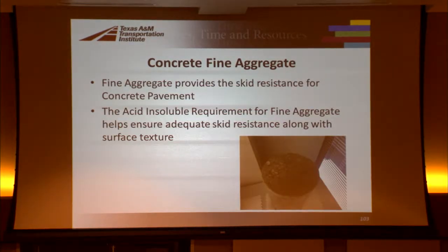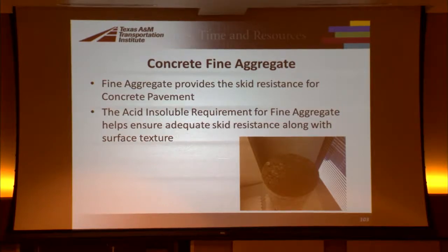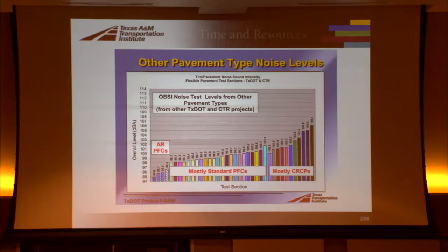Then fine aggregate really provides skid resistance for concrete pavement. An acid insoluble requirement for fine aggregate helps ensure adequate skid resistance. That's why we're using basically siliceous fines to this day, along with the surface texture.